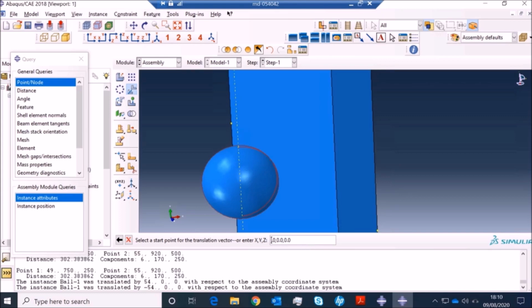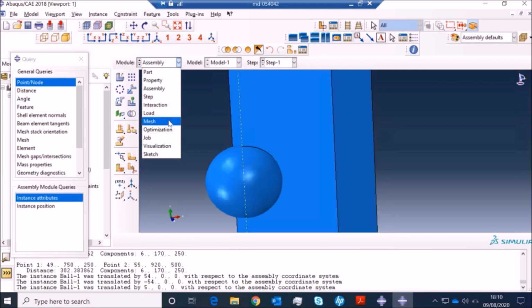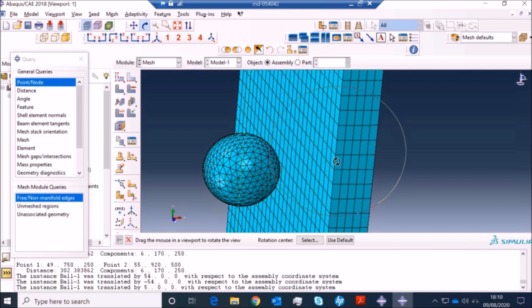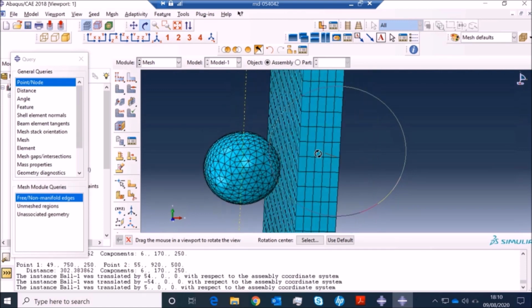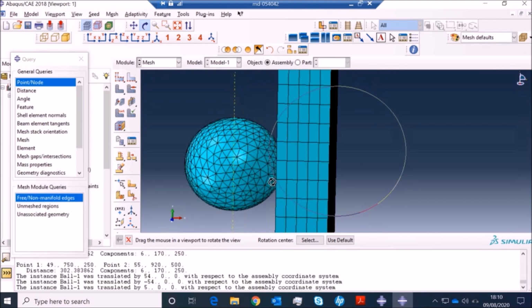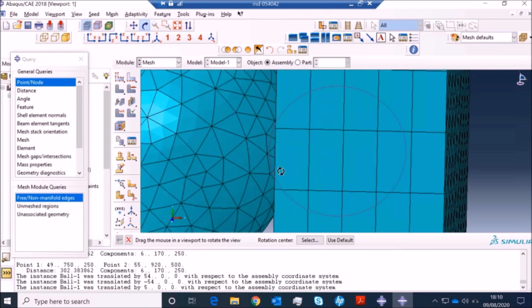In any case, now we start to bring it closer, 5 millimeters closer, so then the clearance will be around 1. So I just give 0, 0 as a starting point, and the end point is 5, so it will move forward 5 millimeters towards the wall, and now the clearance should be around 1 millimeter. I will still try to ensure that it is away from the wall and not touching it right now. So yeah, it looks okay.